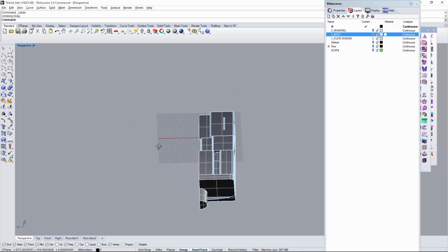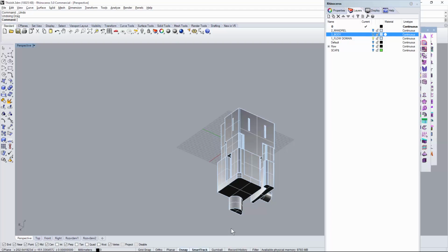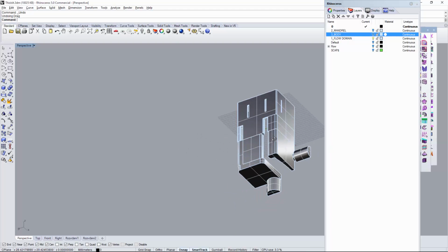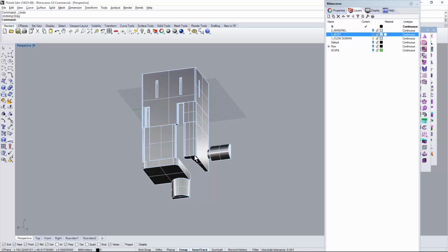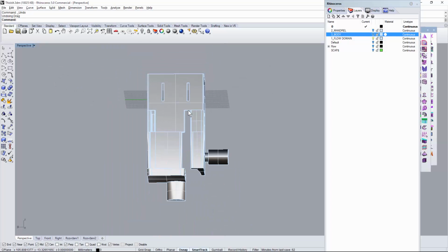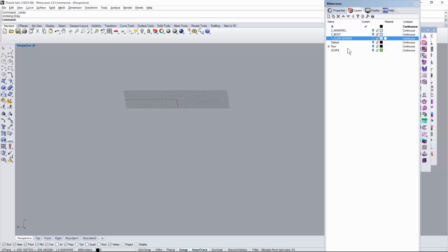We see here 2 polymers coming in, one from here, from the bottom, and one from the side. And of course, if you look at it and if you know that these polymers are different, then probably this is co-extrusion. Everybody would say we can't solve it. No, we can, right? And in fact, if you look at it, they only join right here. There is an interface right there, and probably through here we have some crossflows. We don't have too many crossflows at this merge because this is very close to the exit and the polymer simply wants to leave. We never meshed the whole full flow domain.